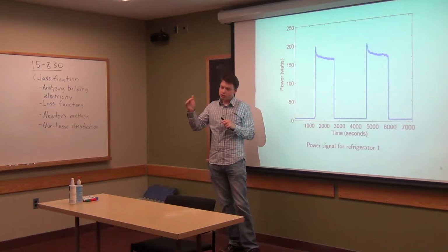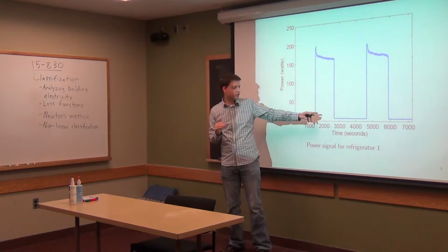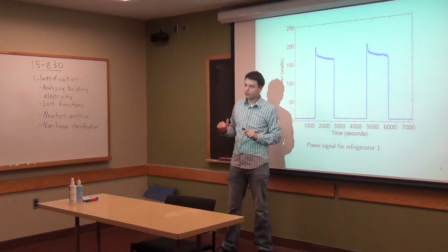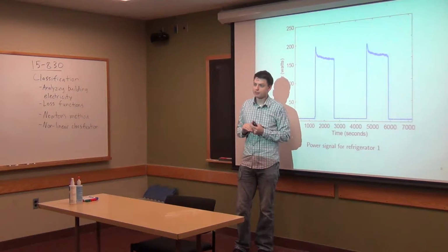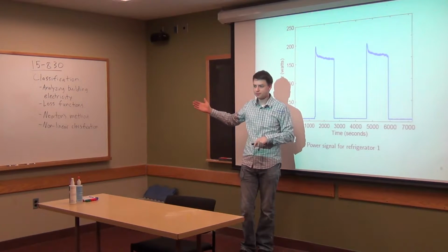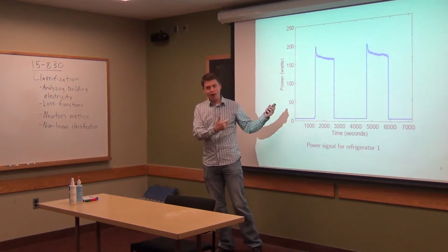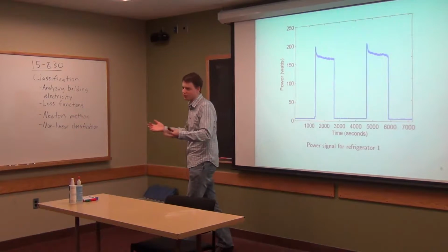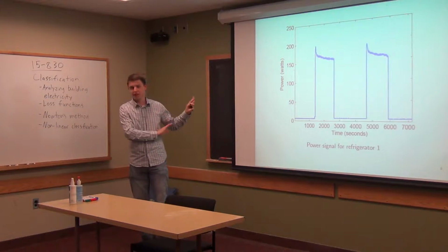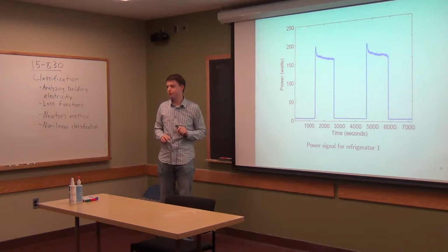That cools the refrigerator. When it cools down enough that it reaches its minimum temperature, the compressor turns off and lets it warm back up inside. And maybe that'll happen quicker if you open it up. And for those that know this well, there's also things like a defrost cycle, which looks a little different than this, but this is basically how a refrigerator works.